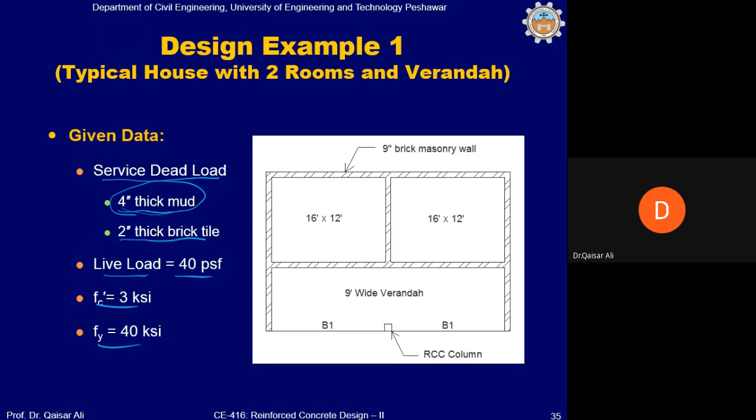अच्छा, अब स्लैब थिकनेस भी आप दो तरीकों से कैलकुलेट करेंगे, एक वन वे स्लैब के लिए और एक टू वे स्लैब के लिए। टू वे स्लैब के लिए आपको पता है दैट h will be equal to perimeter by 180, that is, perimeter multiplied by 12 plus 16, divided by 180. इससे आप कैलकुलेट कर सकते हैं, ये जरा कैलकुलेट करें, शाबाश। हरी अप। सर ये 3.7 इंच आ रहा है। 3.7 इंच। ओके,